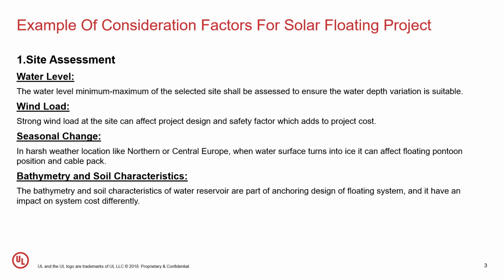A recent example of wind load effect, if everyone remembers the accident case in Japan in 2019, where the solar floating was damaged by the typhoon. Seasonal change in colder locations like Northern or Central Europe also shall be considered, because let's say if the water turns into ice, it may affect the floating arrangement, because the solid ice can pack up the array of the pontoon.